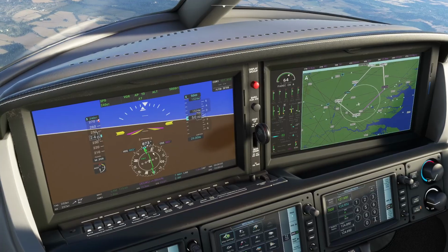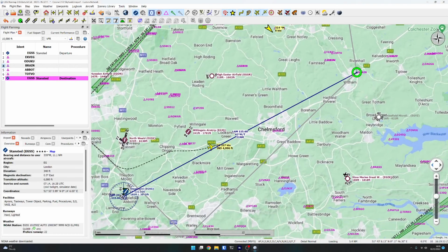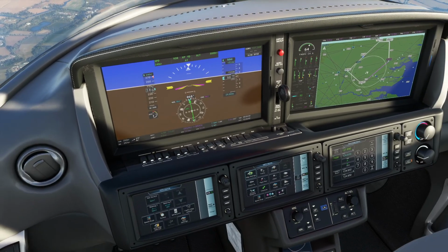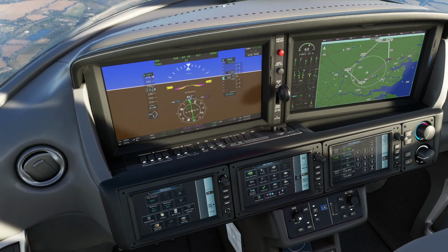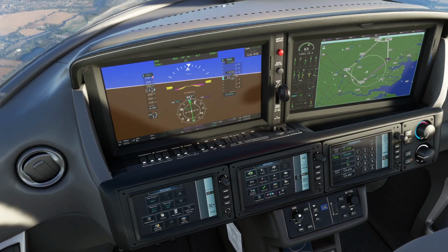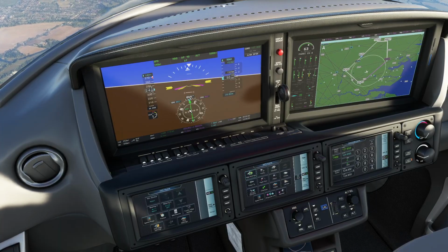So we're flying the 62-degree track. You can see it happening here, look. The aircraft is centering up on the 62-degree line completely automatically by following the radio beacon from the VOR. But what we could do at this point, just to show this is possible, we'll go and turn the heading round to the direction we're going again. So we'll go back to heading mode. The reason we use heading mode is so we can change this mode over with nothing reacting.